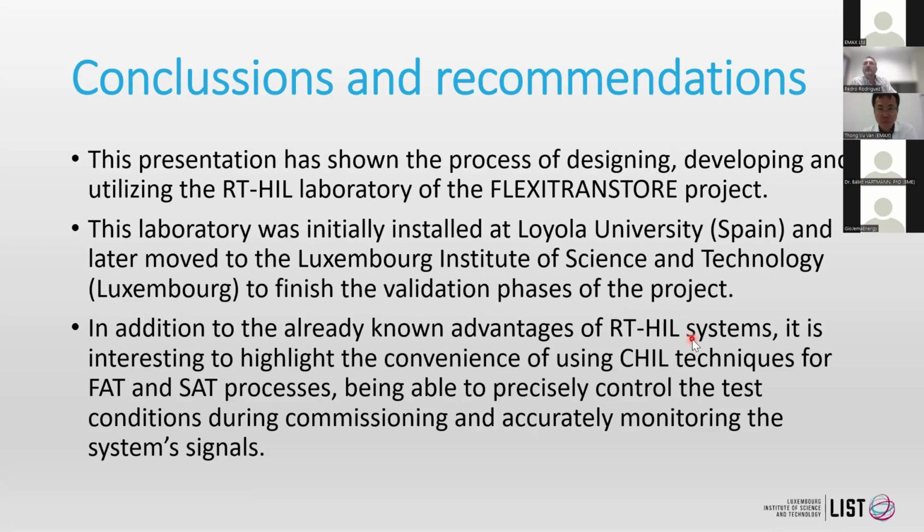Therefore, at the end of the day, when the batteries were commissioned after the site acceptance test, we had almost 90% confidence that the battery would respond well under real operating conditions. Afterwards, when they were operating during the validation stage under real operating conditions, we were able to monitor the system, and in case there was any discrepancy or variation, we were able to simulate the case in our simulator running in parallel.